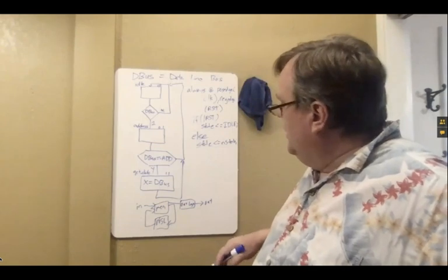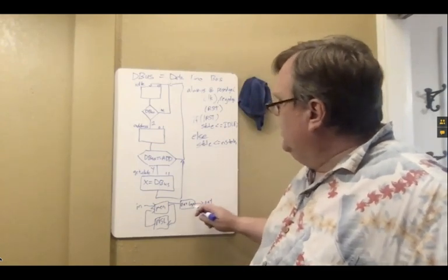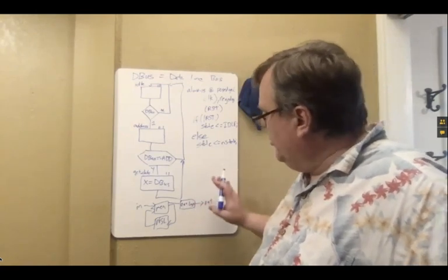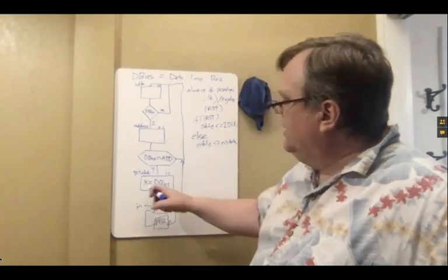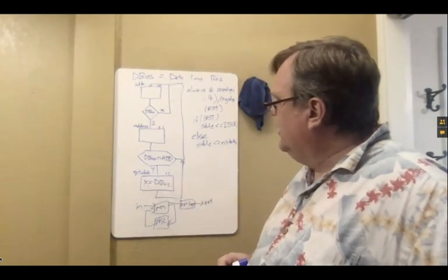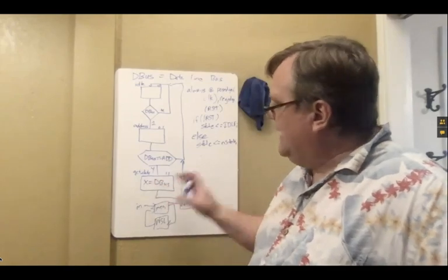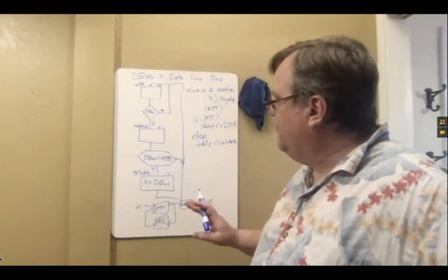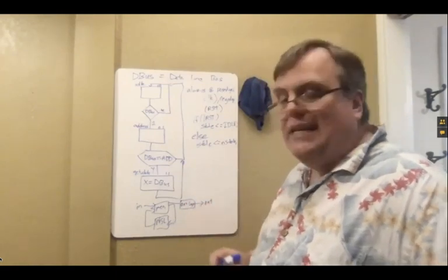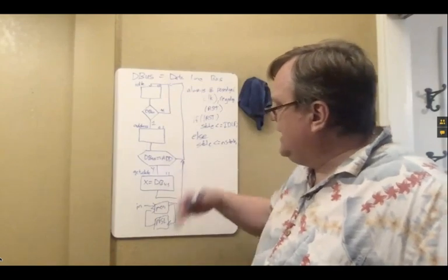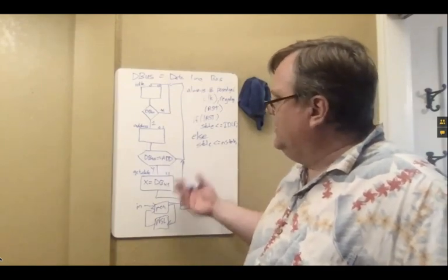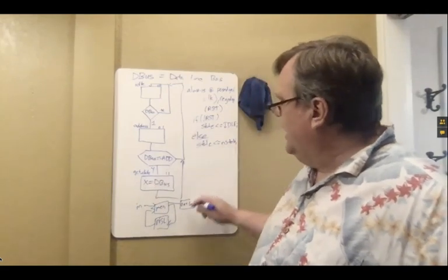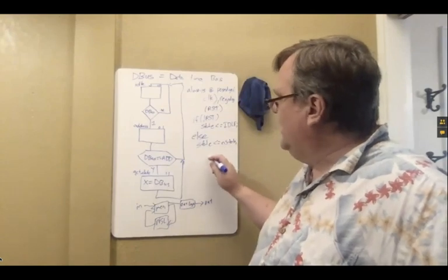Yay. Let me do, in this case, my output logic. I'll just make a comment. There's no real output logic that I'm having to deal with. My output's going to be set here, and output is just getting a value. I'm never looking at it. I don't check the data. So I don't need to do anything funny for this. So I don't need any output logic. If I'm going to be checking it, I might make another internal variable, double X or something that I could check, and my output logic would be like assign X equals double X.